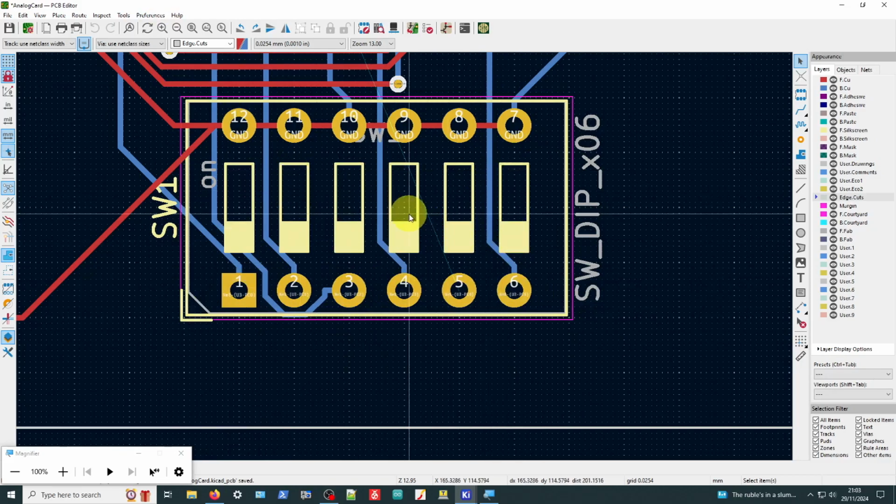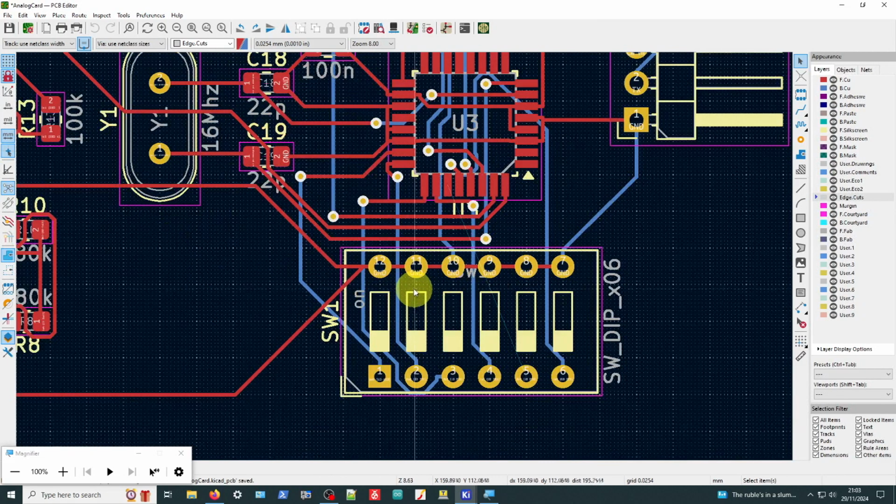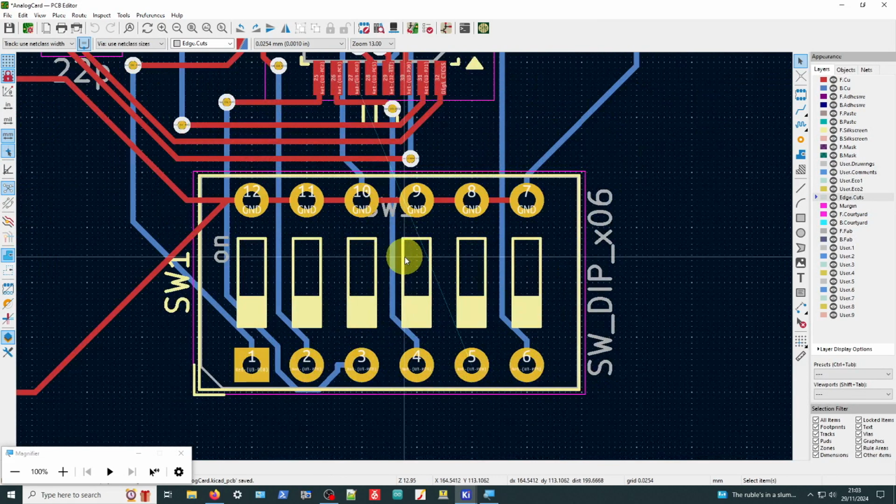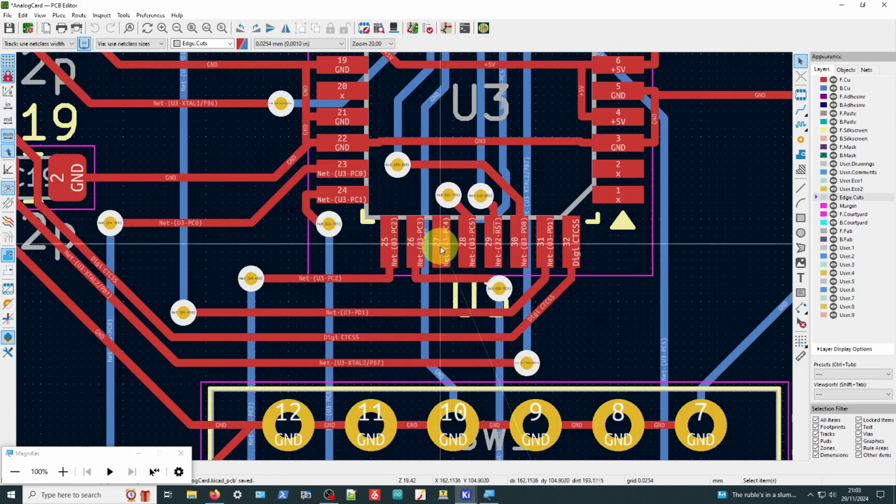If it was a 3 or 4-layer board, it'd be no problem at all, but we don't really want to go that far with this project and just trying to keep it to a 2-layer board. So yeah, it's got itself into a situation where there isn't really enough room, not without moving everything around. You could do it manually. If I move these tracks down here, I'd have enough room to put a wire in, and I could probably somehow figure out a way around it.